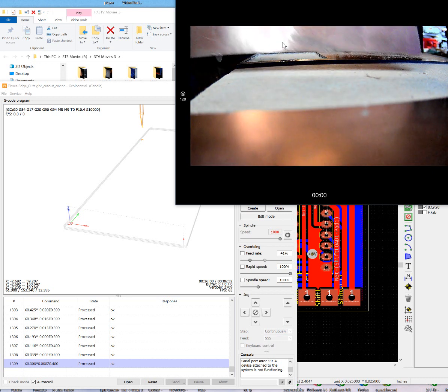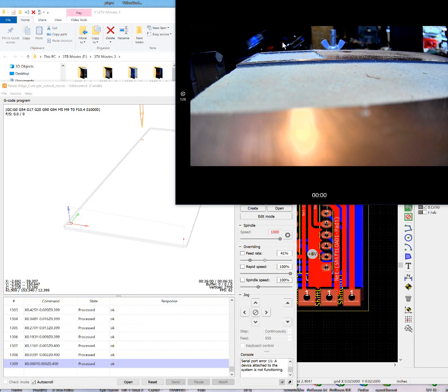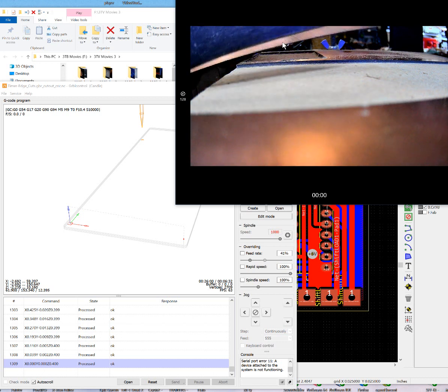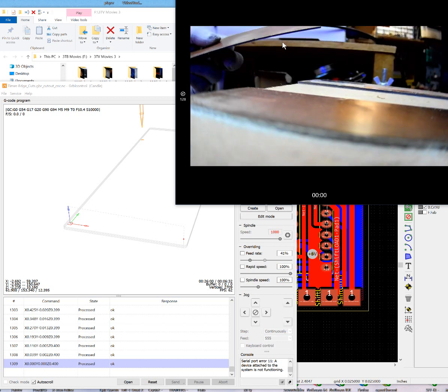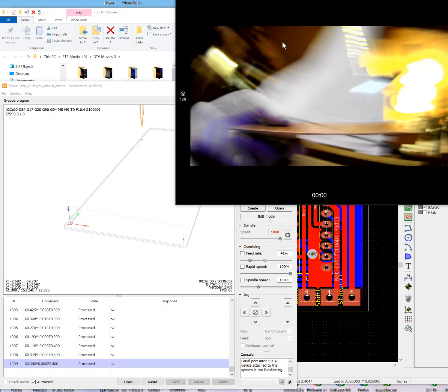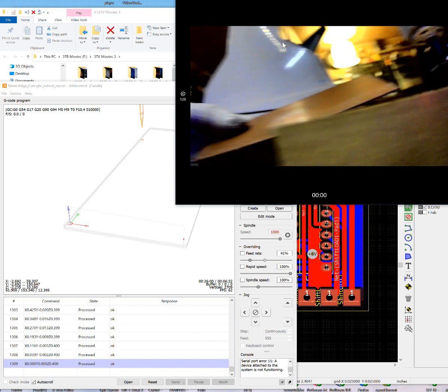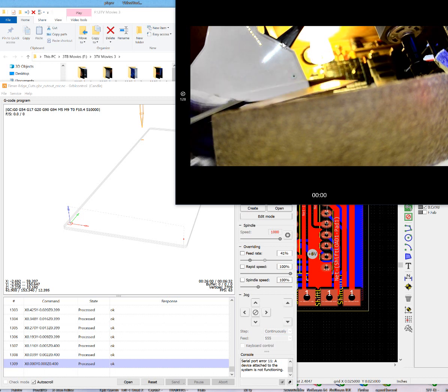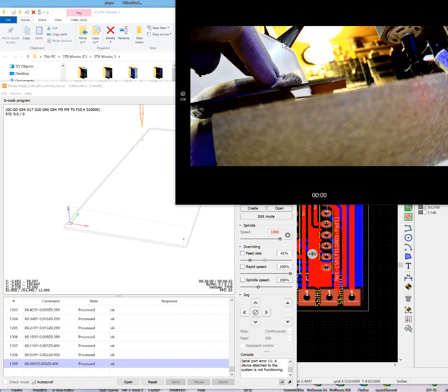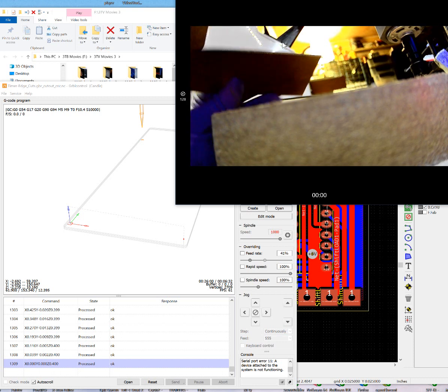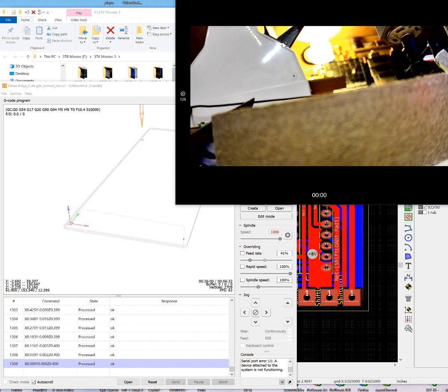And this is going to be the hop side. Now I do advise that you get your little flat bastard file like I talked about in an earlier video. Go around these edges, because you want this thing to lie very flat on your board. If you don't, you don't want any kind of give that the tool can press down on.